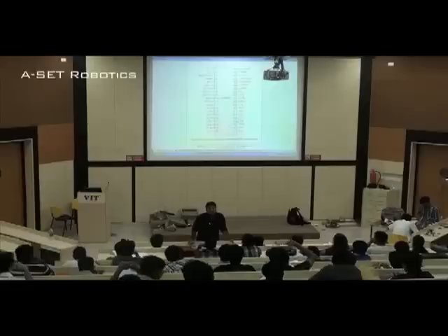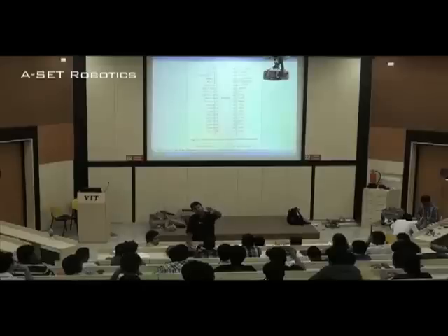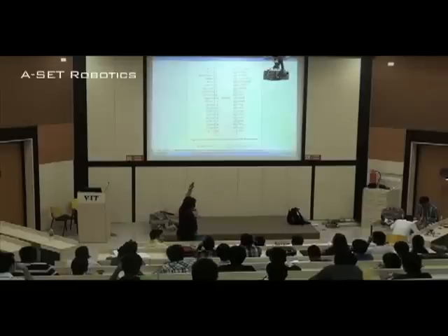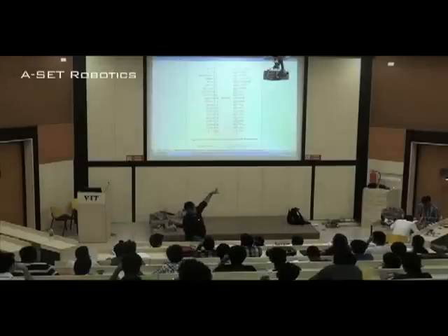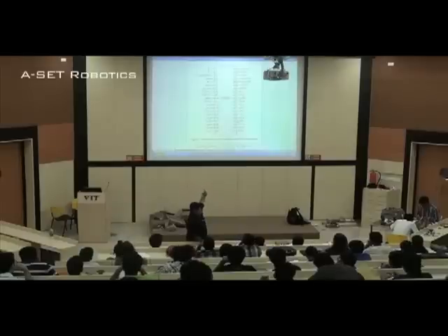A8 to A15, it is used to increase the... See, we need 16 address lines, but we have just 40 pins, and we need all these functions in this microprocessor, so we cannot hide any of these. So what we did was that the first 8 bits were multiplexed.